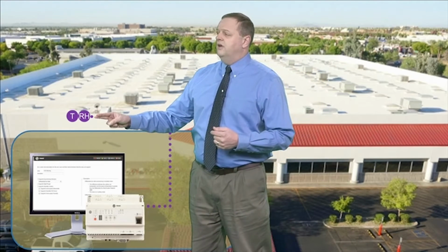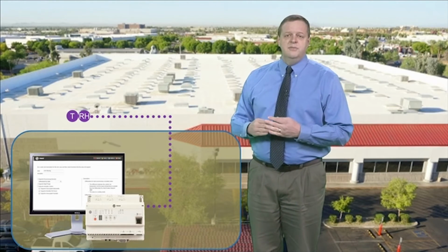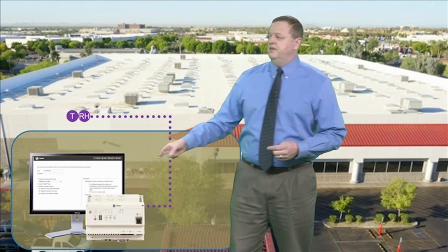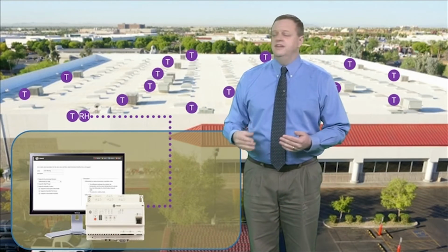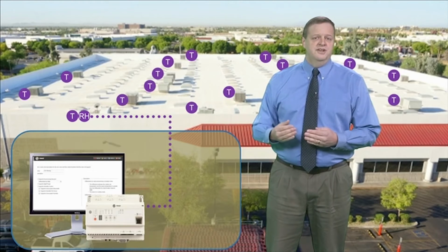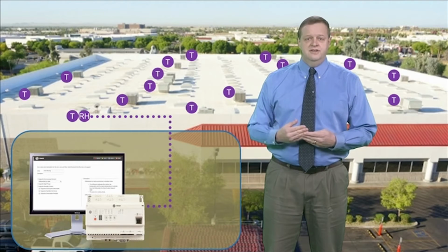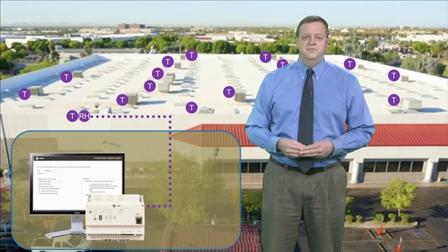If a building automation system is used, a single set of high-quality sensors might be installed to determine when to enable economizing. A decision that is then communicated by the BAS to all the rooftop units. Each unit still makes its own decisions about cooling or heating, but will only enable its economizer if the BAS tells it that the outdoor conditions are suitable to do so. Usually the individual units are still equipped with outdoor temperature sensors. So in the event that communication is lost from the BAS, this allows each unit to still operate its economizer in a standalone mode until communication is restored.